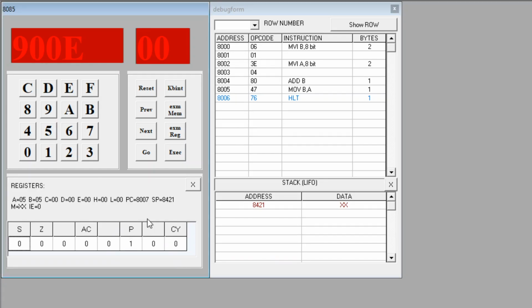Type the halt instruction. If you do not type the halt instruction, you will run into a loop. Not exactly a loop, but since there will be no halt instruction, the microprocessor will not understand where to stop. It will keep on executing, even though the data byte at every memory location is 00, and it will keep on decoding 00 infinitely after it reaches FFFF. Fine.